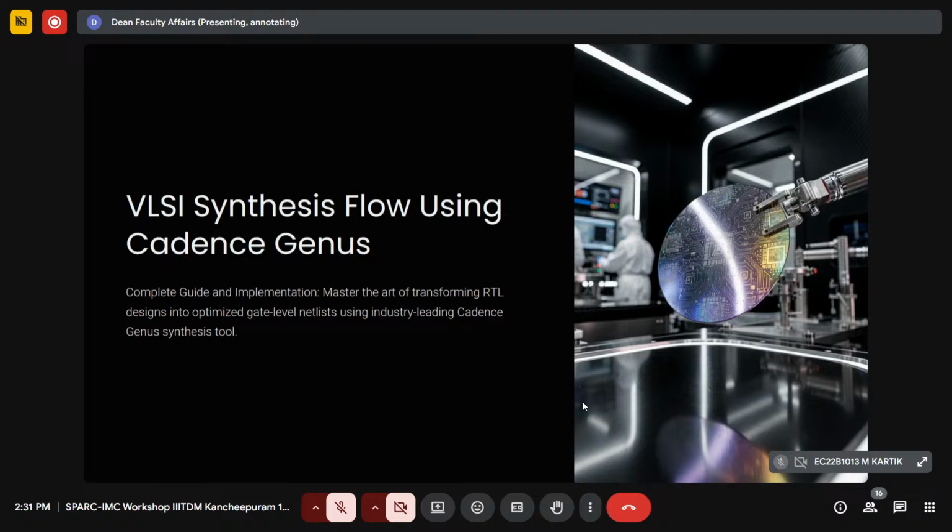So basically, when you clock them, you are expected to meet the timing between the two flops. Only then can the data be captured from the launch to the capture flop correctly, right? Which means the performance of the design is basically the timing point of view. So timing is the second most important thing in design, starting from synthesis, right? What is timing? Timing is nothing but, if you have a component and data is passing through that component, the time taken for the data from the start point to the end point is called the delay, right? So this is called delay.